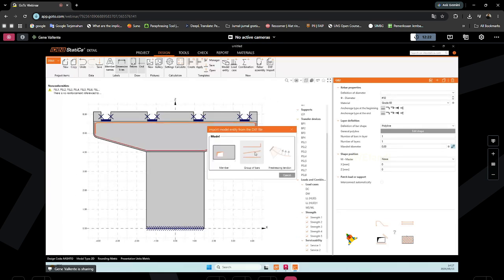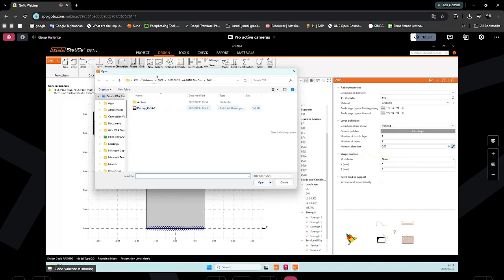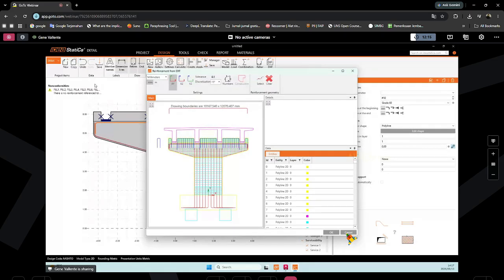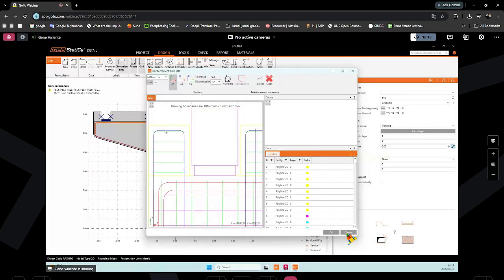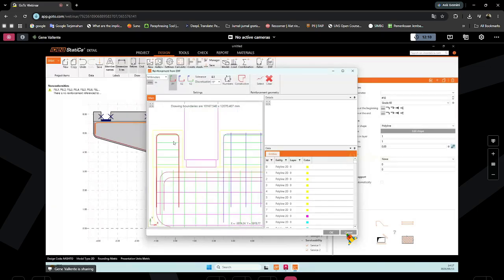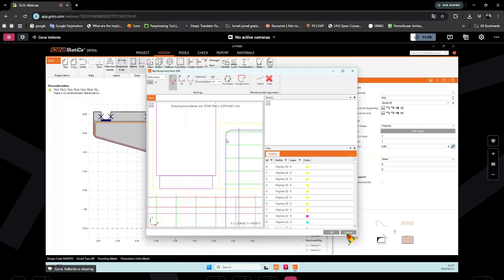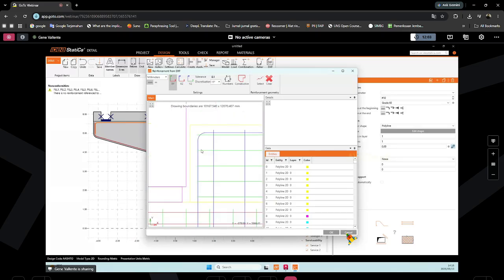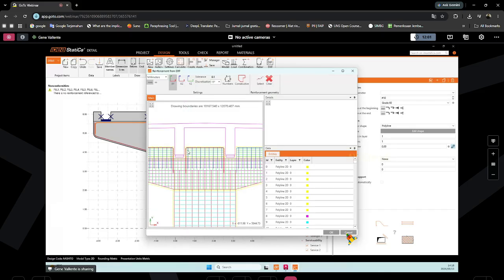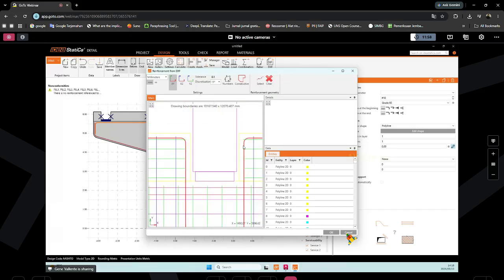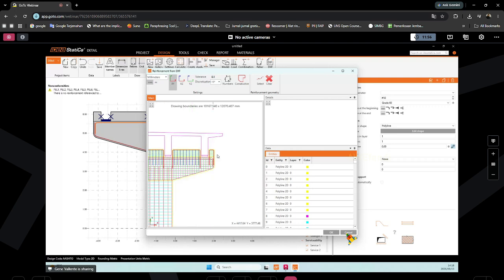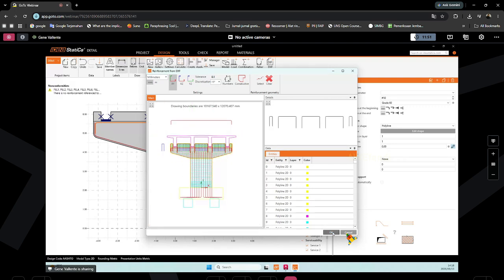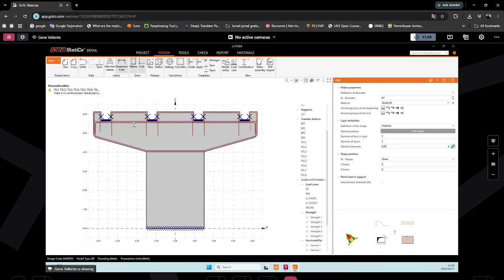So again, I will just continue with reinforcement here. For example, I want to get rid of these non-conformities right here. I will put in this reinforcement. Again, I can also make use of the control button instead of simply doing it one by one. I can just press the control button and then select the required reinforcement. See, I just click on select and I can click on OK. So all this reinforcement will also be added.